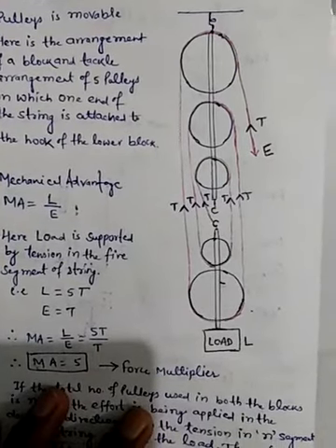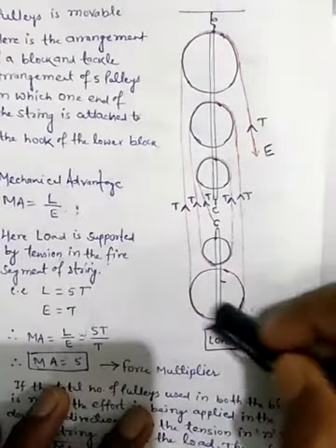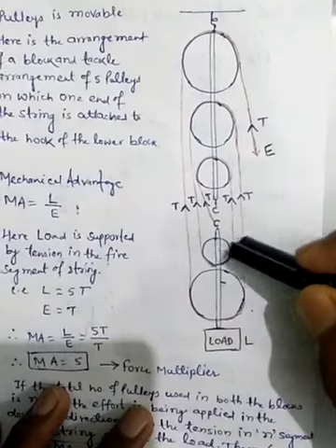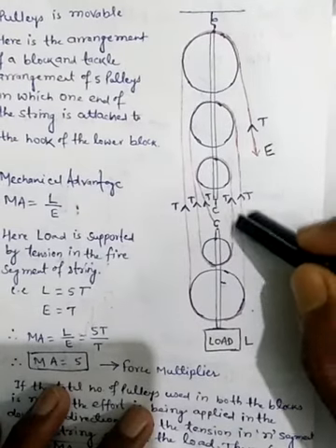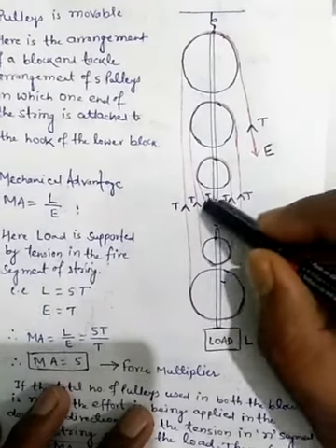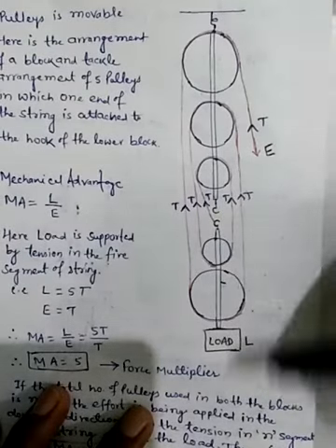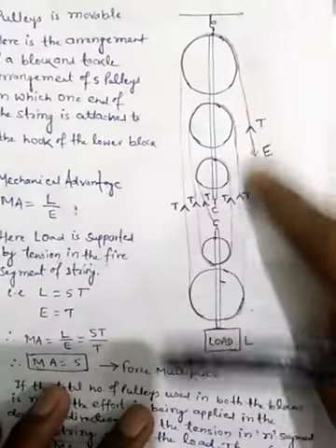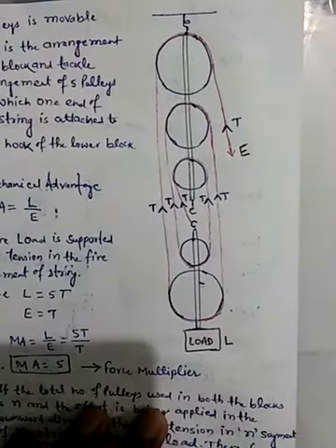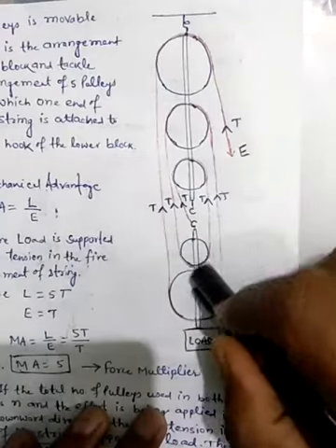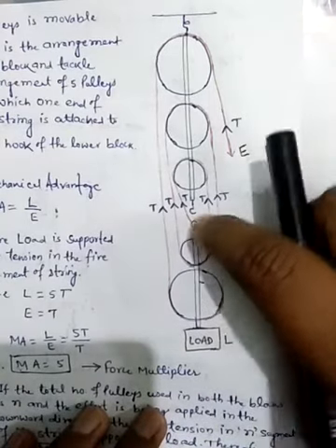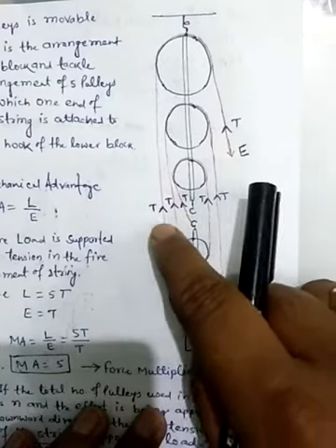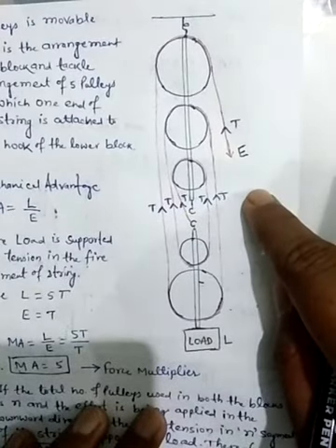For calculation of velocity ratio, if the movable block is moved upward with a distance x, then each of the five segments is also displaced by x distance for the tightened string. If this movable block moves upward with a distance x, it loses x distance in each segment.